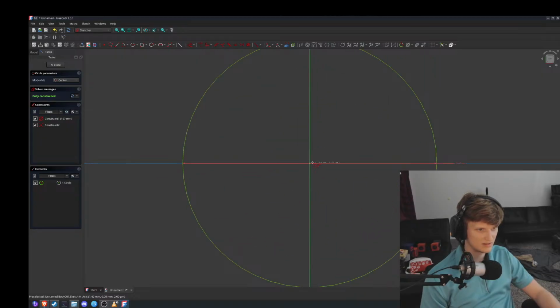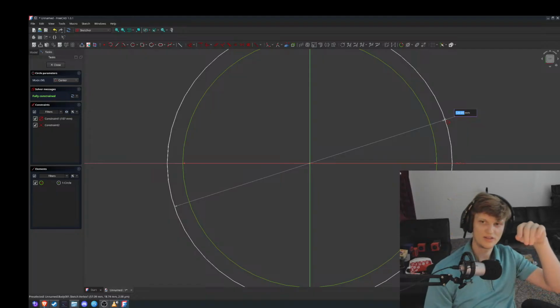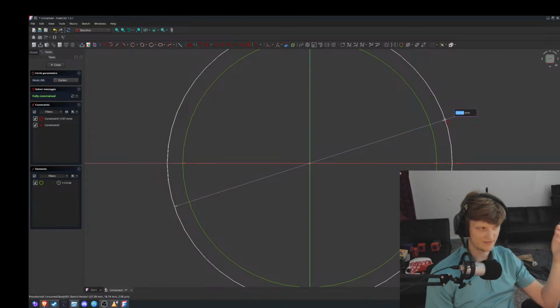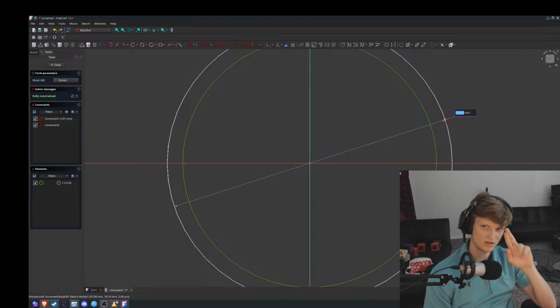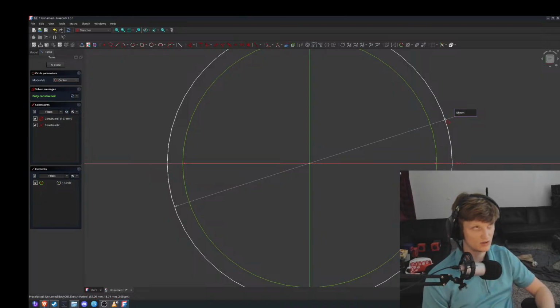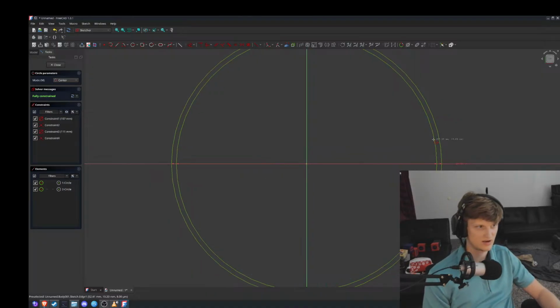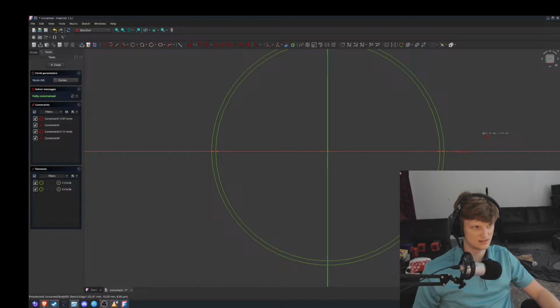All right, we need this to snap to 100. The rule of 3D printing that I have found is a 2 millimeter wall is the best wall you need. So I need 107, it'd be 2 on each side. So 109, 111. So 111 millimeters would be what we want. That would be the size of our disc.